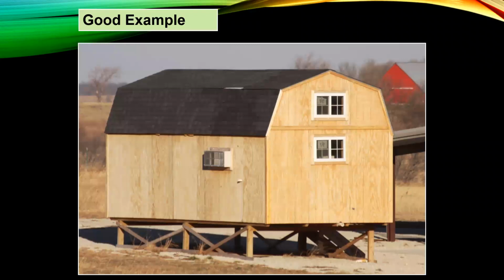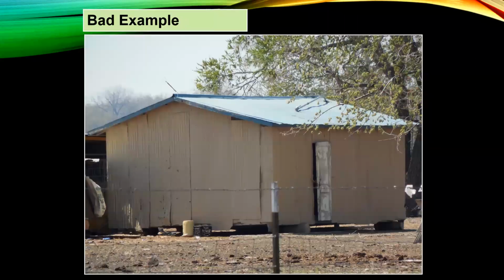And then, so here's a good example. This one is not wet flood proofed, it's elevated, and you can see the utilities were elevated. So this one was actually done correctly. We would need an elevation certificate to be able to verify that it was built in compliance.